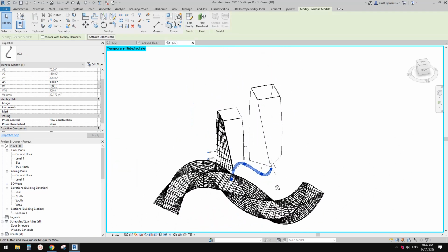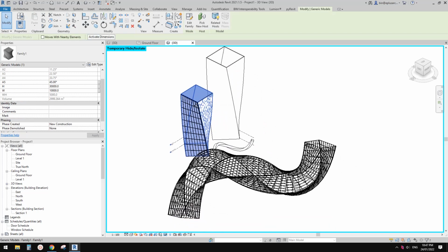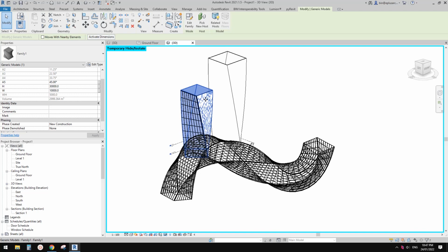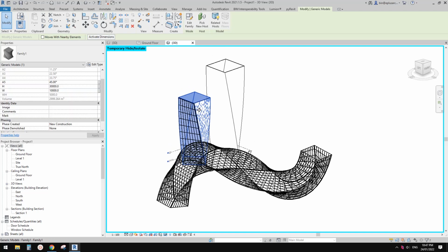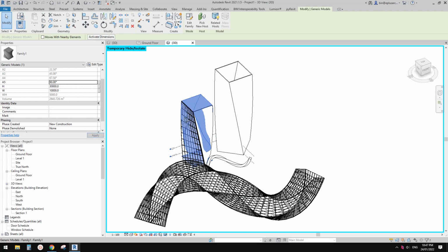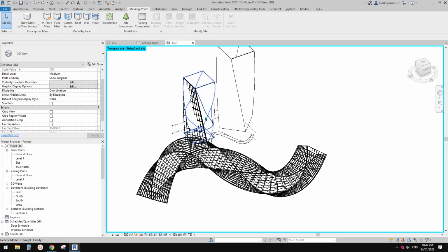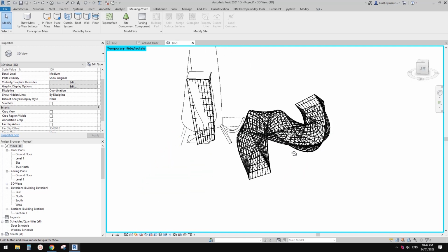Okay, so let's recap. We tried an adaptive family with 2 points. This is just 1 point with the height, and then it's a vertical that twists a little bit, and we noticed that some angles don't work, some do. And also, instead of having a vertical, we added some extra points and made them adaptive points, so we can create some interesting shapes.